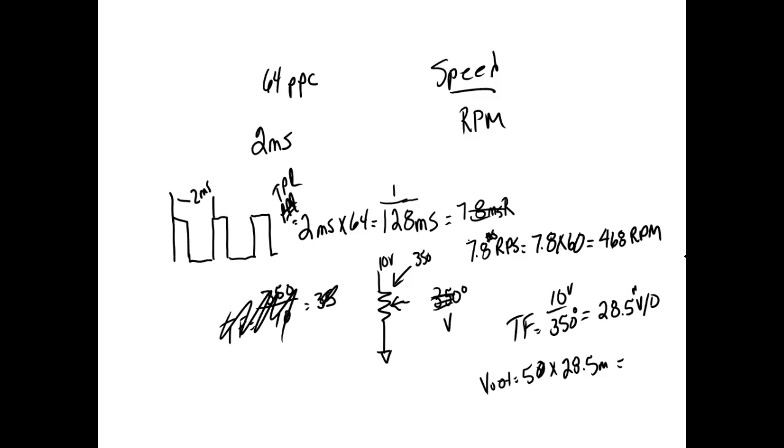So whoever designed that thing, if my thermistor goes out and I put another thermistor in there and it's not the same one, what did I just do? I screwed up my transfer function, right? And that's built into the little controller, so I wouldn't think you would be able to reprogram it.